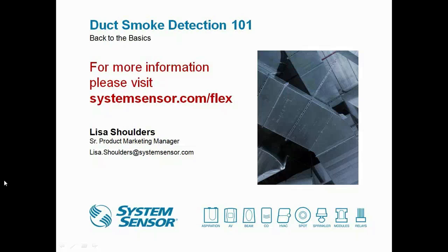You want to ensure that the sampling tube covers a minimum of 2/3 of the width of the duct. If it is doing that, you'll still be getting a large enough sample of the air that's moving through the ductwork. But obviously, having it extend all the way across is good practice as well.